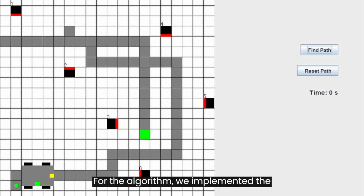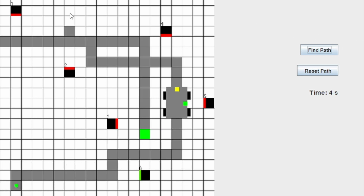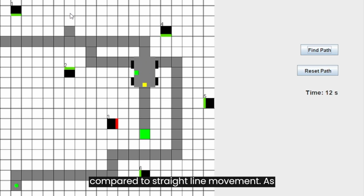For the algorithm, we implemented the A-star algorithm with Manhattan distance. We also implemented some penalties for the algorithm. So the first penalty is about the turn. We add more cost to turn compared to straight line movement.